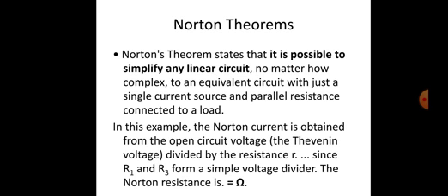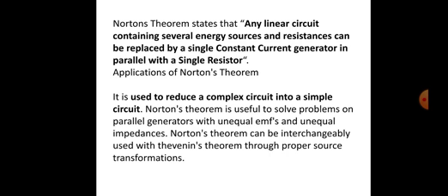What is a Norton equivalent circuit? Norton's theorem allows us to temporarily remove the load resistance from the original circuit of figure 1 and reduce what's left to an equivalent circuit composed of a single current source and a parallel resistance. Next, the load resistance can be reconnected to the Norton equivalent circuit to allow calculations as if the whole network is a simple parallel circuit.